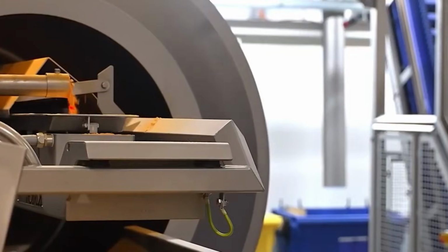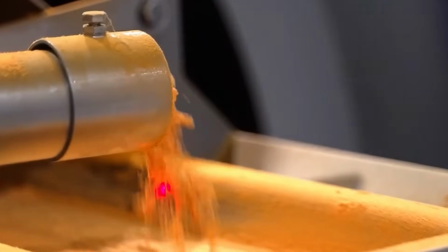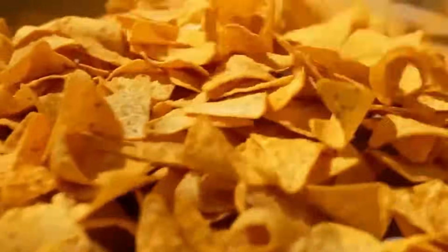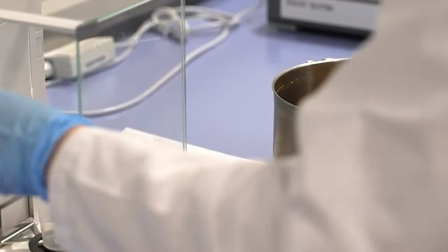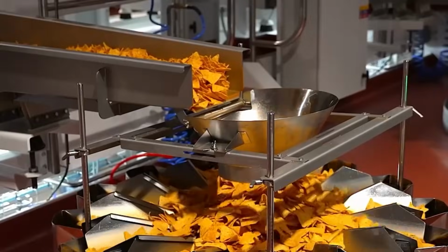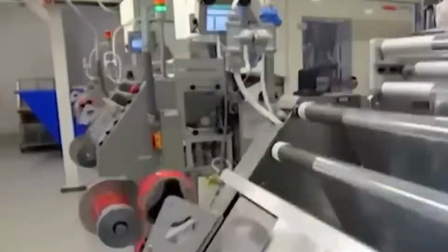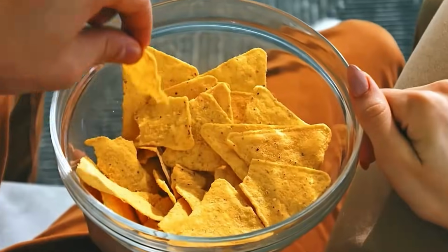The fryer is filled with high oleic vegetable oil, typically corn or sunflower oil, filtered and recirculated through plate filters to maintain clarity and reduce polar compound formation. Oil temperature is held at 180 to 190 degrees Celsius. Chips enter on a submersion belt and are fried for 50 to 90 seconds, depending on their moisture content and thickness. During frying, final moisture is reduced to less than 2%, and texture is developed through rapid dehydration and surface